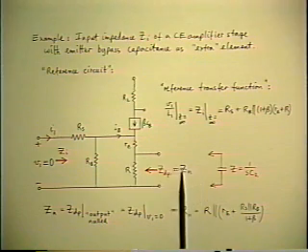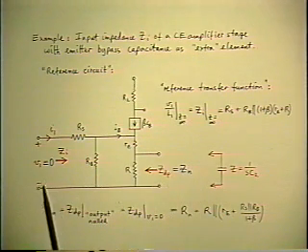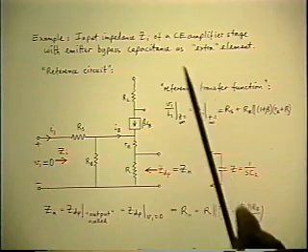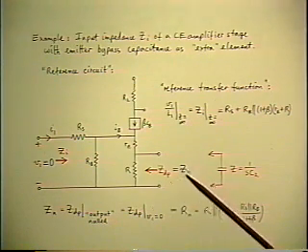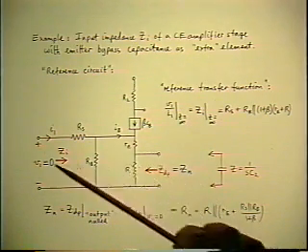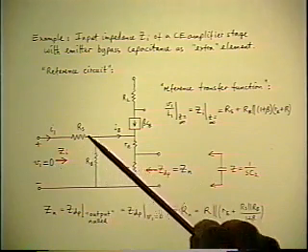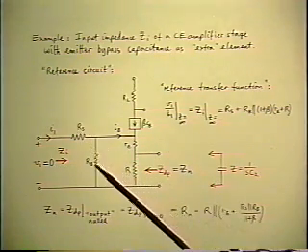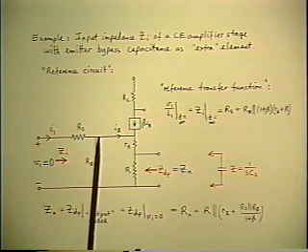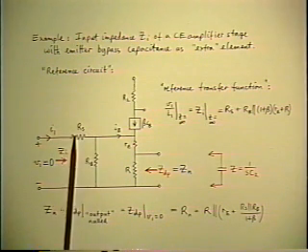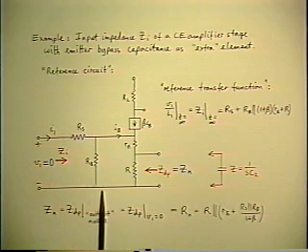Now, this is a little tricky, isn't it? Because you've got to remember there's a current source out here, and you're adjusting two sources until the voltage across that current source nulls. But when you're looking in from the second source and asking what is the impedance, it thinks that the RS is back in parallel with the RB, because the voltage at the right-hand end of RS is the same as the voltage at the top of RB, and the voltage at the left of RS is the same as the voltage at the bottom of RB, namely 0.